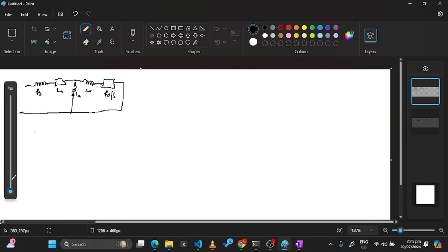There are two ways you can go by it. You can make assumptions. So if the question says you can make assumptions but state your assumptions, then you can say that you are assuming this branch. The solutions in the slide assume this branch. So we are looking at the first part of the question where we are analyzing this. So the line voltage is 415, so the phase voltage is 240 volts. Okay, so the solution in this slide actually ignored this. Then if you ignore this, then the circuit will reduce to what?